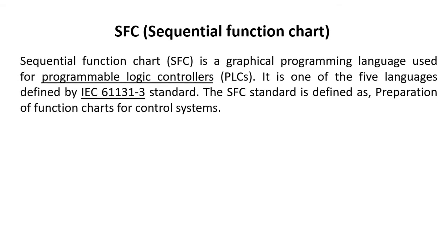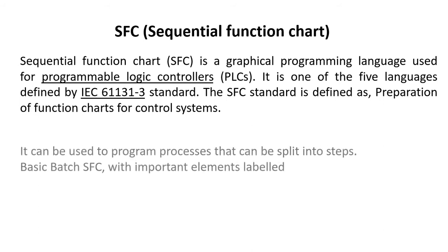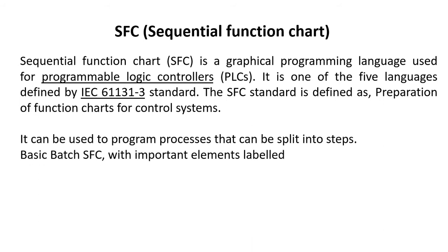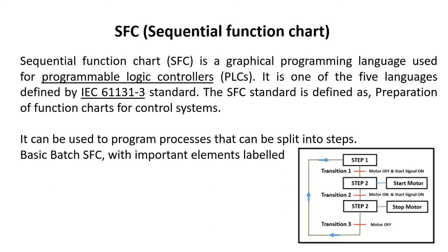What is SFC? SFC is nothing but Sequential Function Chart. It's a graphical programming language for PLCs. It is one among the 5 languages defined by the IEC 61131-3 standard. The SFC standard is defined as preparation of function charts for control systems. It can be used to program a process that can be split into steps.